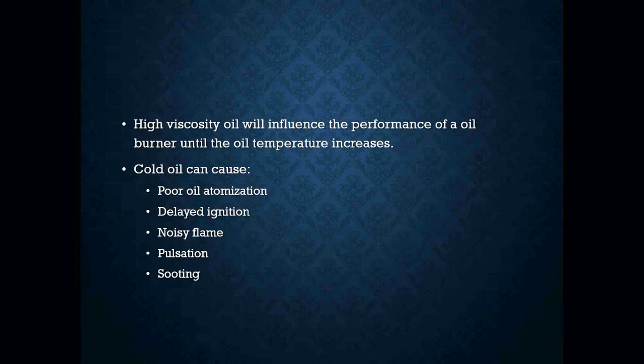Okay, high viscosity will influence the performance of oil burners and how they react to things. As the oil starts to warm up and starts to flow, the viscosity is going to change, which is also going to change the performance of an oil burner. Okay, cold oil can cause a lot of different issues in oil heating.